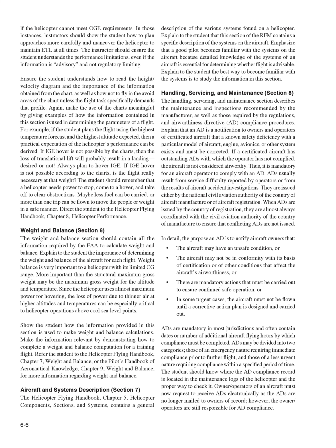ADs are mandatory in most jurisdictions and often contain dates or number of additional aircraft flying hours by which compliance must be completed. ADs may be divided into two categories: those of an emergency nature requiring immediate compliance prior to further flight, and those of a less urgent nature requiring compliance within a specified period of time.